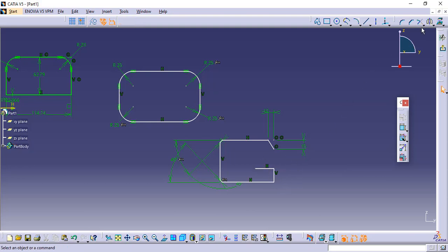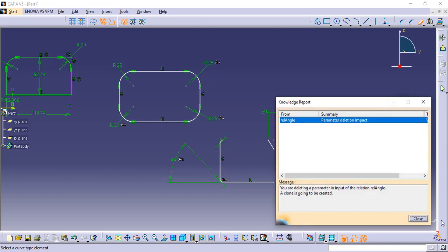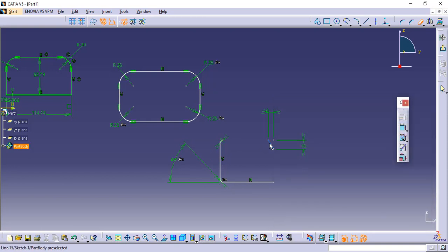Yeah, and the second point is quick trim. You can trim anywhere in the line. I will explain first. Like the line is, this is the one line, second line, third line, fourth and fifth. This is not a joint, or it is not fixed together. This is not a single line construction. So I can make it in parts. If you want to trim the whole figure, double click, use multiple times. The dialog box is open because of the dimensions.